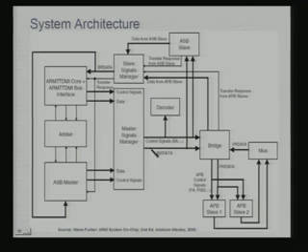The control signals communicate from the master to the bridge, and the whole idea is that this data which comes from here can go to any of these slaves. If you remember, there was a response signal flowing in. So, the slave sends the response signal, and that response signal goes to the ARM core or to the other master.